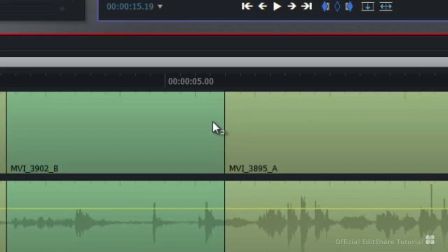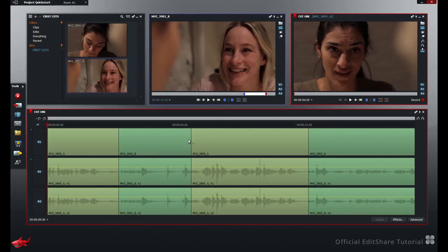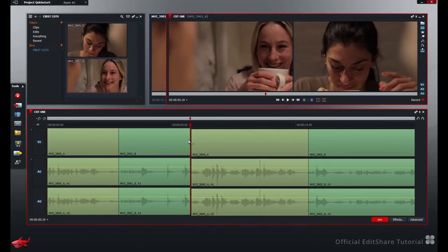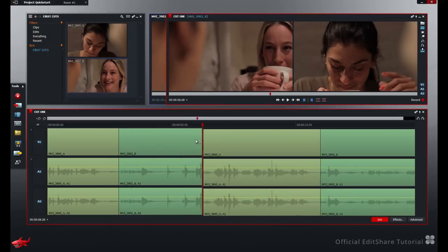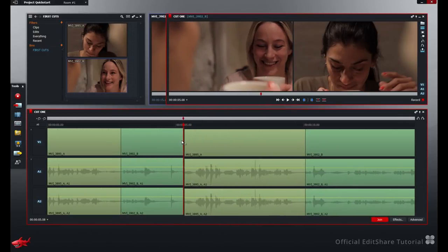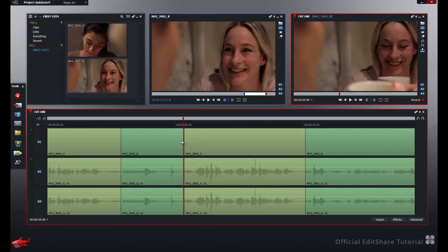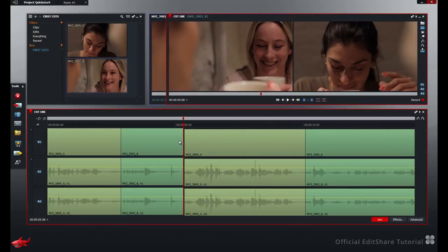On the left, you'll trim the out point. On the center, you'll trim both sides of the media. And on the right, you'll trim the clip's in point. To modify the cuts, either click and hold and drag left and right. When you release, the cut is rejoined. If you wish to permanently unjoin, click once.